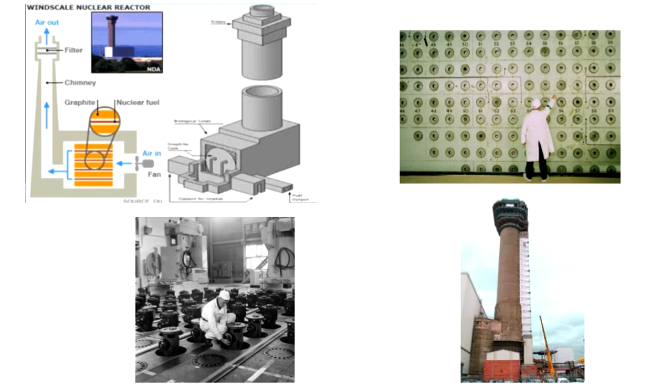Efforts to discharge the burning cartridges into the water ducts were unsuccessful. Operators continued their attempts to diminish the flame with liquid carbon dioxide. Finally, shutdown fans were turned off and the water slowly doused away the flames. At around 3 p.m., the water was turned off after the fires completely subsided and the reactors were cold.